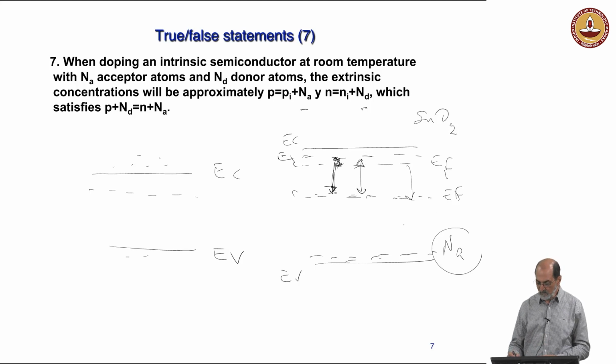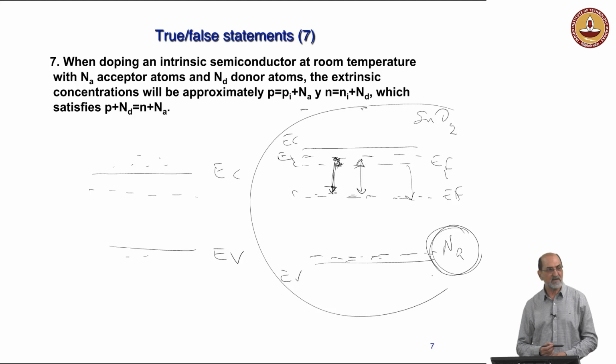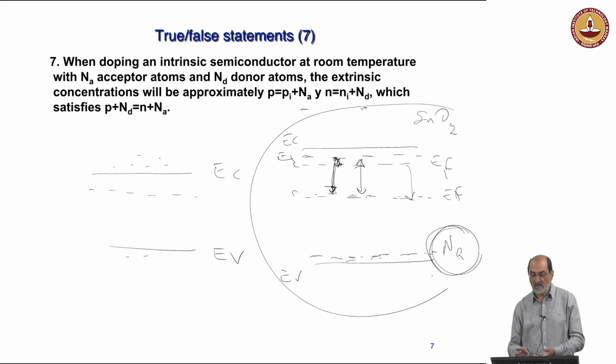So as you're pushing the Fermi level down, including acceptor levels, the Fermi level goes down, and automatically it's easier to form oxygen vacancies, which are going to compensate what you have done. So that is the reason why it's very difficult to make p-type tin oxide, for example. And this happens in any wide-gap semiconductor, essentially.